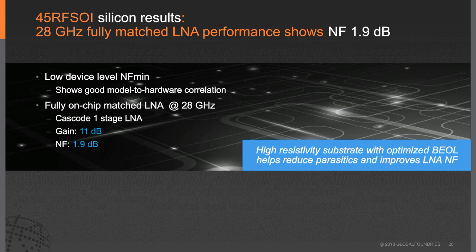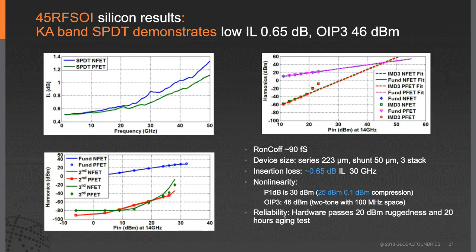And then this is for the switch. We have achieved insertion loss of 0.65 dB with an IP3 of 46 dBm, Ron-Coff of 90 femtoseconds. And again, we passed reliability at 20 dBm ruggedness testing as well.